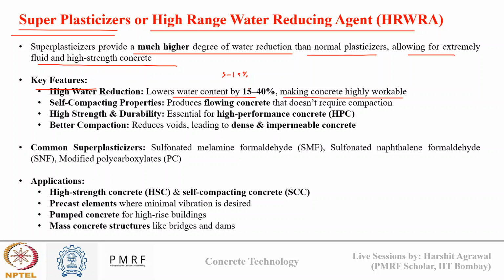So we can reduce water content by 15 to 40%, and we can maintain the same level of workability, or even increase the workability. They are used in self compacting concrete. They produce flowable concrete that doesn't require compaction, as they impart a very high level of workability.